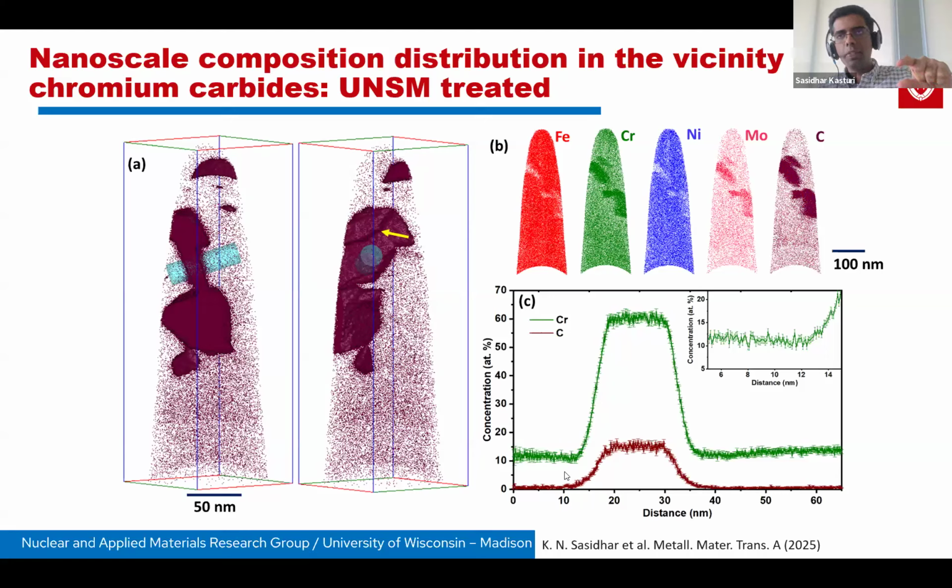Professor Sridharan can correct me if I'm wrong, but the thickness of the plate is close to a half inch, and it's a big fusion weld. Technically, the heat affected zone is strictly heat affected. It's not affected by diffusion from the solid state weld. In the fusion weld region and very close to that, you will have chemistry differences.